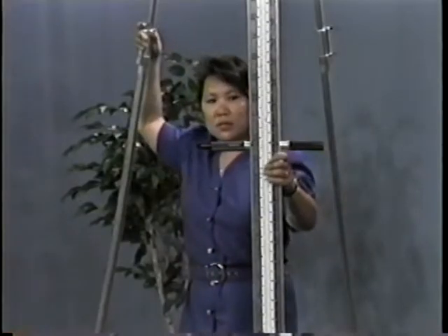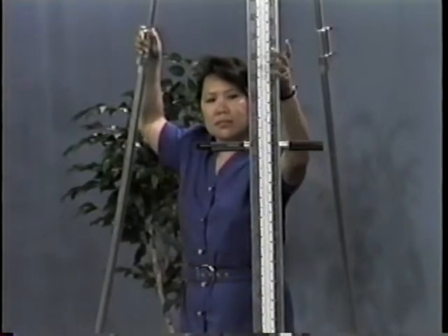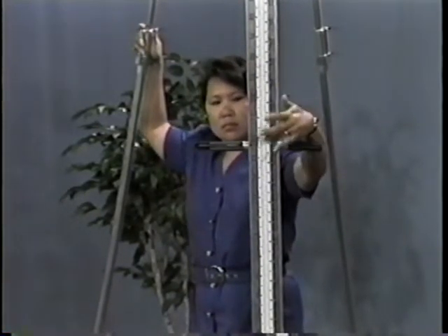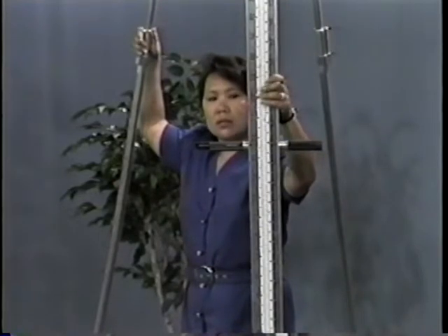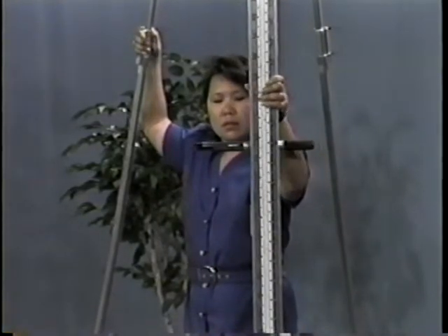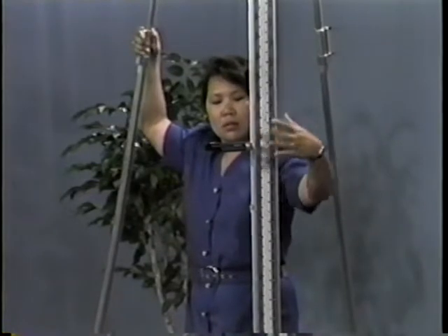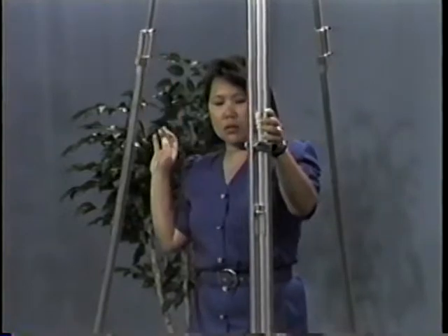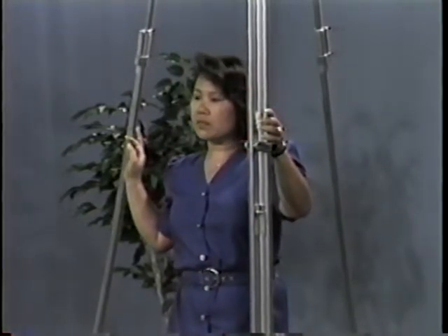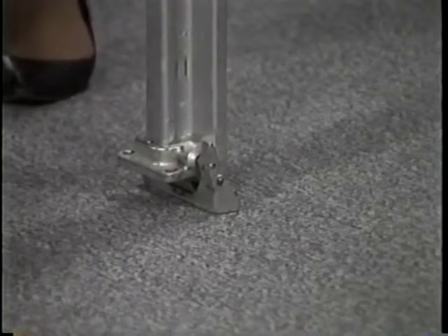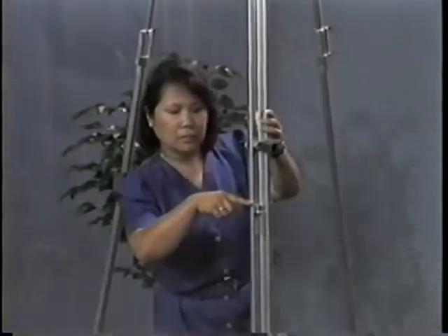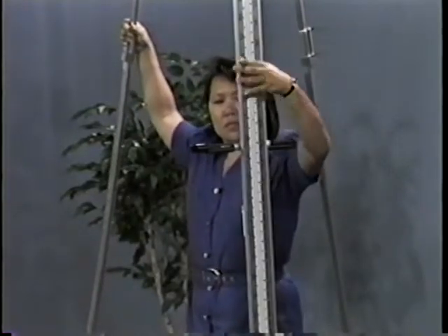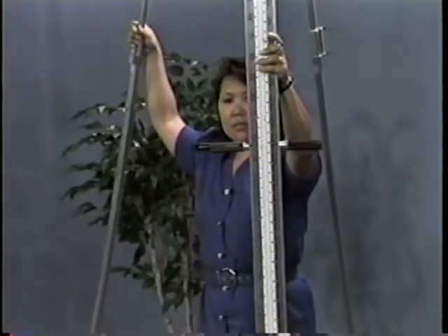This is a first order leveling rod, also known as an INVAR leveling rod and meter rod. This one is aluminum with an INVAR tape with graduation marks in meters. INVAR is a metal alloy that resists expansion and contraction due to temperature fluctuations. Springs are attached to maintain a constant tension and stability. The rod has a hard metal foot and sets up on a heavy metal boot. Once placed on the boot, with the use of the bubble level attached to the back of the rod, the legs adjust and clamp to maintain the rod on a stable vertical plane. These rods are made in matched calibrated sets.